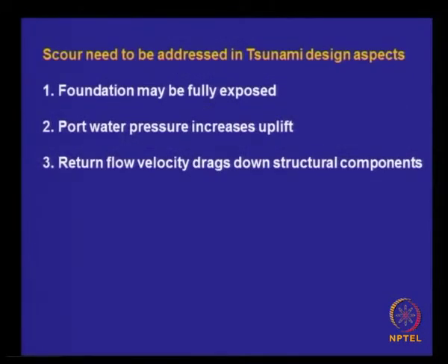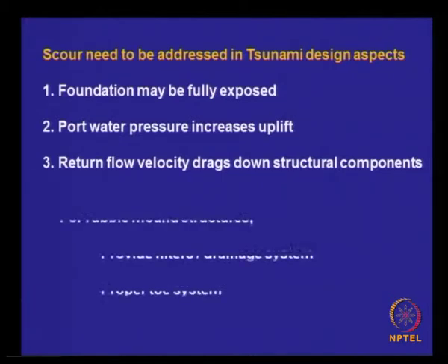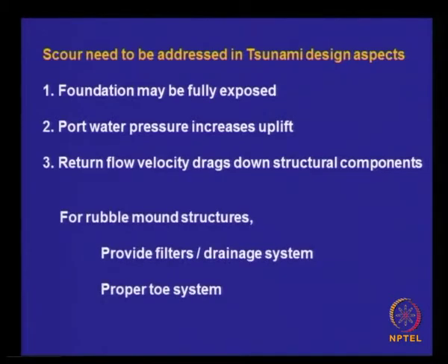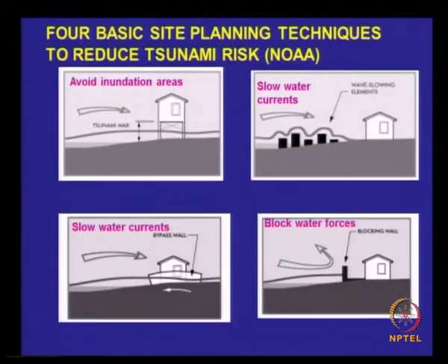Scour needs to be addressed in tsunami design aspects. Foundation may be fully exposed, pore water pressure can increase uplift, that is another problem. Return flow velocity drags down structural components. These are the effects due to the scour taking place. For rubble mound structures you may need to provide filters, drainage systems, and proper stone layers, which we have already discussed in some of the earlier lectures.